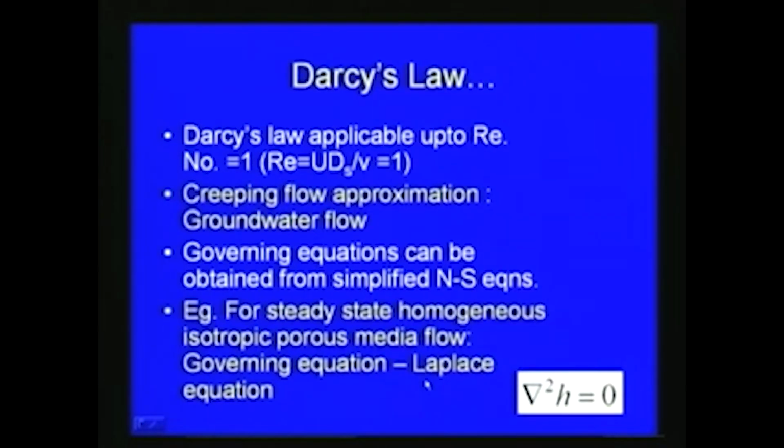So here what we did is, we tried to use the equation which we derived for the pipe flow, and then between the sand grains we tried to get the actual velocity, and then we obtained the velocity, and that is Darcy's law, which was proved by Darcy through experiment. You can see that this Darcy's law is applicable up to a Reynolds number generally equal to 1, where Reynolds number here is defined as U ds by nu, where ds is the grain diameter and nu is the kinematic coefficient of viscosity.